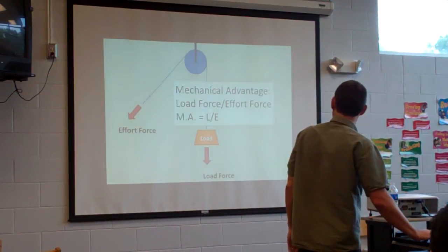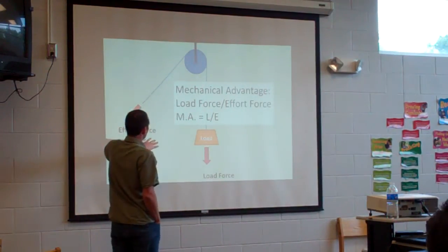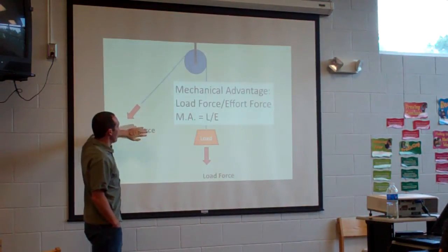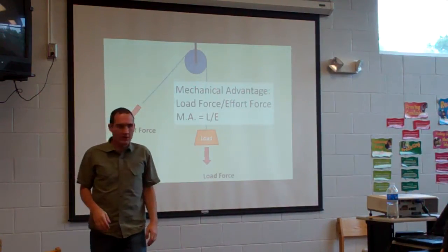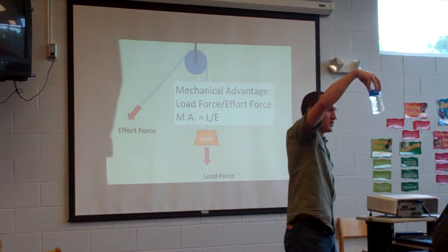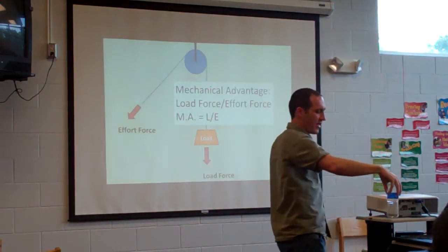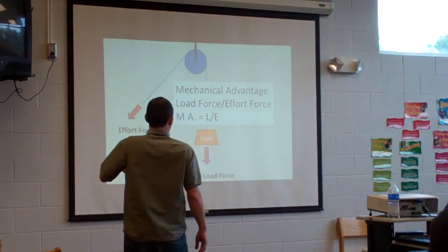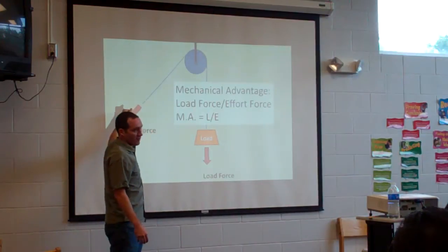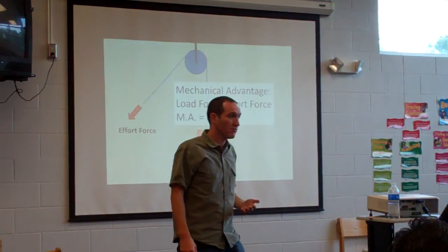Everybody with me? Okay, this is one way to talk about mechanical advantage. Mechanical advantage is simply this force over this force, right? If I just lift an object, if I just lift this water off the ground, the load force and my effort force are the same, so that's a mechanical advantage of 1. There's not really any mechanical advantage. But if we put simple machines together in the right way, we can lift a heavy load with a very small force, and then we're going to be getting a mechanical advantage that's much more than 1. All right?